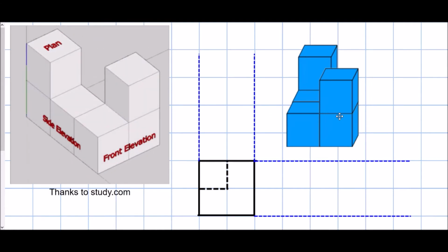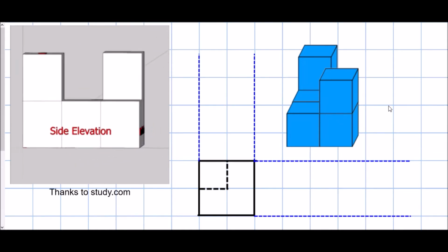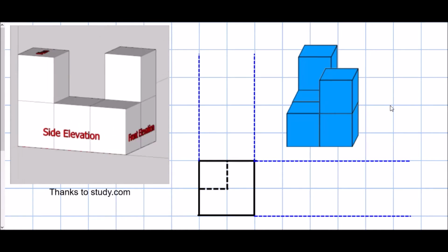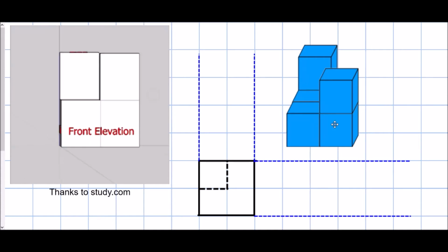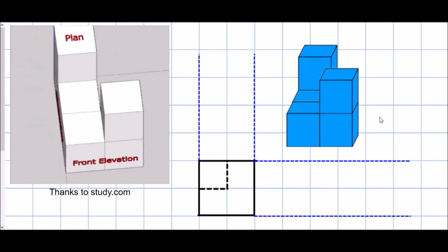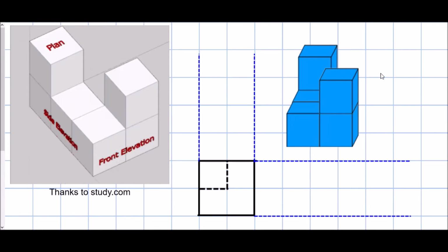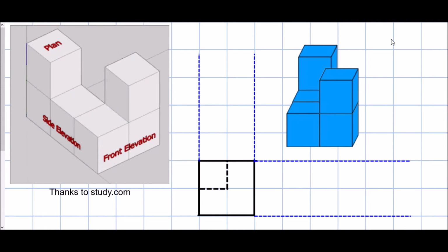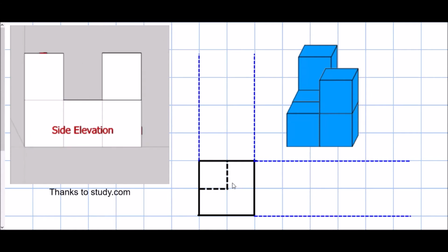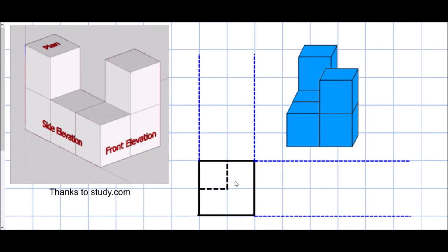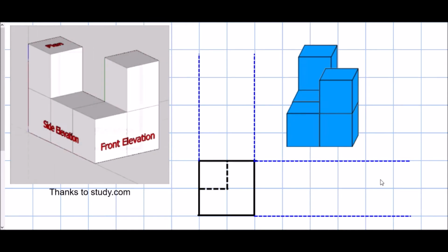Now what you will notice is as you look at the different shapes, even though there is depth involved, once we start looking at it directly straight on, the shapes become flat. This is a way of showing what we can see from those different angles. I'm going to show you a method for doing this, and this is something you may have seen in design technology, as this is an orthographic view. It is showing the front to begin with, and then using the dimensions of the front to design the plan view above and the side view to the side.